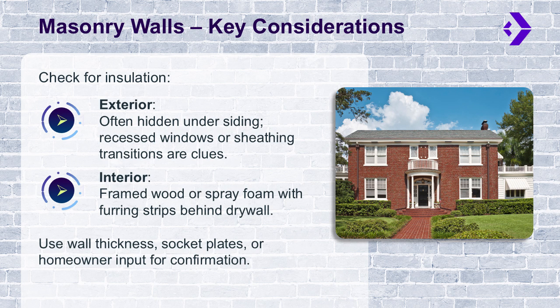In each case, you need to work a little harder to confirm what's behind the scenes, using a thermal camera to see stud framing, or look from above in the attic or below at the band joist to give you a sense of what's inside the wall.